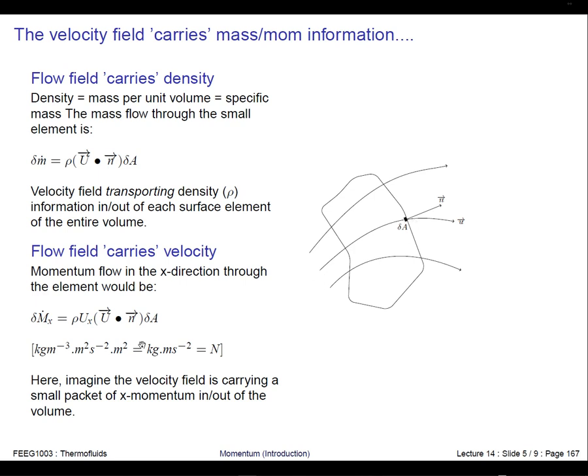It's quite interesting to look at, and we define this in the same way that we define the mass conservation: here's our momentum, and here's our normal to the area, and this is the thing that's carrying some momentum out of the control volume at this particular point. And if you had your area on the other side pointing out this way, you'd have some momentum being carried into the control volume on this side, and you'd have the opposite sign on this thing.